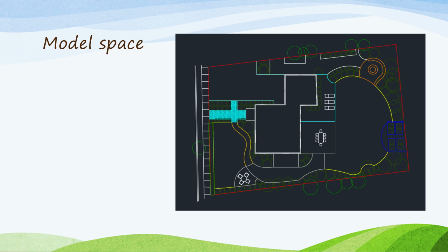We also used the hatch tool, which allows the user to add pattern to the inside of an object. For this project, we used the hatch tool to add a herringbone paver pattern to the front walkway. We also used modifying tools such as the trim, move, rotate, and copy tool. The trim tool is used to remove overhanging pieces of parts of the project. The other three tools do just as their name suggests: move, rotate, and copy.